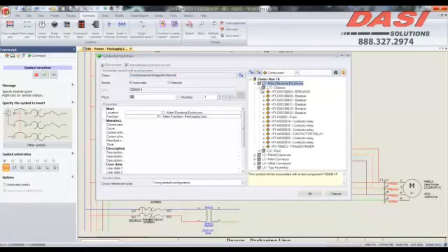I'm just going to go ahead and grab this and just start dropping things in. And if I've already got them associated somewhere in another part of the software, then I do not have to give them a new number. Here I'm going to go ahead and give this disconnect a specific number. So it is going to be a disconnect circuit breaker. Let's do disconnect, and it's going to be 614.